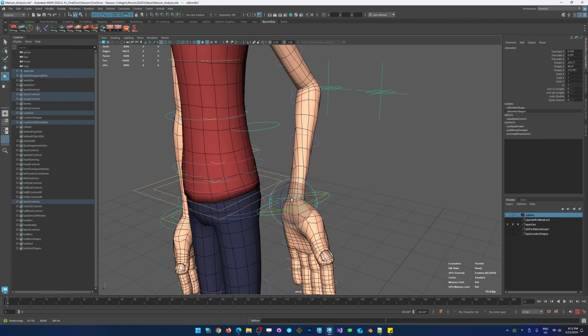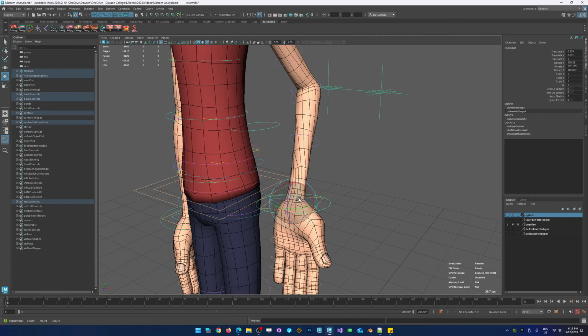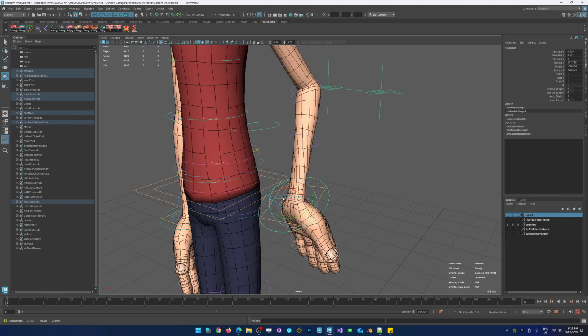It's an issue with the twist bone, at first is what I thought. So there's some sort of issue here. But what's actually happening is in order to get these nice clean shapes so that when you go to extremes, it pushes out like a little, it has a blend shape basically to keep these nice shapes, and it activates based on values from the rotations, but it's using the Euler values almost directly.